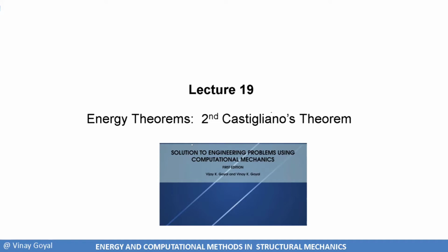And then from there, I took the principle of virtual work and specialized it for a case, and that case is the total potential energy theorem. I was able to make that specialization by taking the most general theory, the principle of virtual work, and making two fundamental assumptions, the first being that the deformation is conservative. The deformation goes through a conservative process, meaning that the body of material, when you load it up and you remove the load, will be fully elastic. It will come back exactly where you started before you started applying the load. So that's one of the biggest ones.